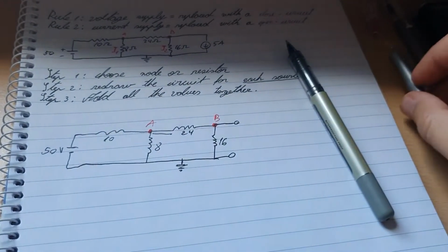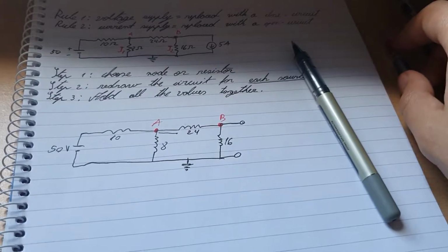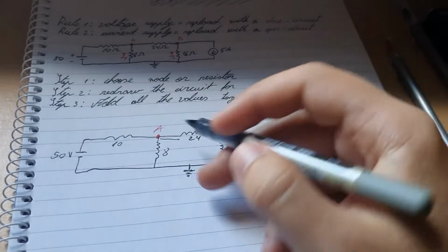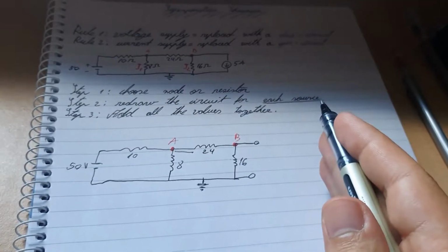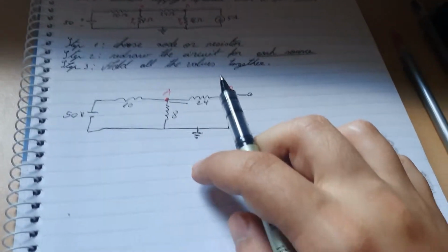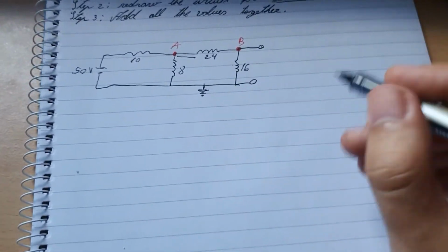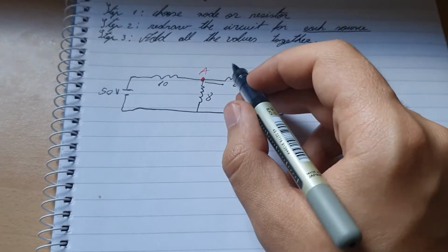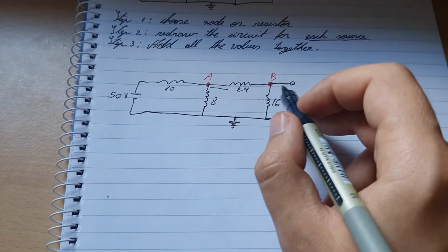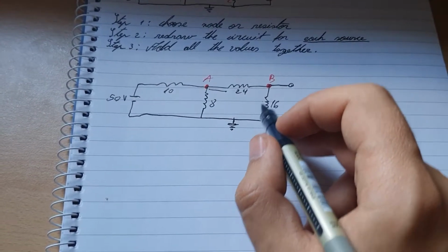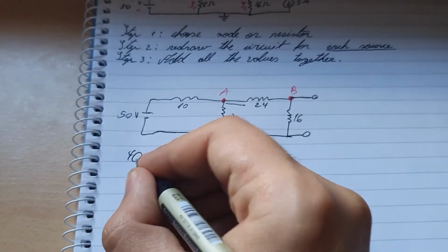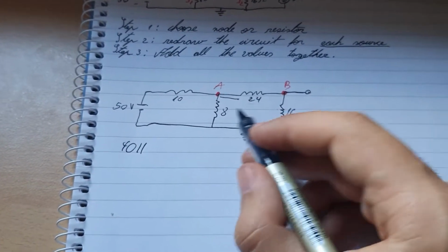Now, what we want to find out is the current through this circuit. And the way we do it is by finding out the total resistance. We'll take it from the right side all the way to the left side. So we got 16 and 24. That means these two are connected in series because this circuit is open, so there is no current flowing through it. There's nothing in this side, so it's no longer in parallel. It's a series circuit with those two, so that will be 40 in parallel with 8.